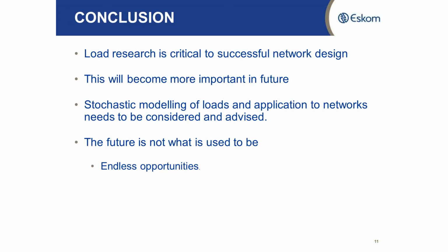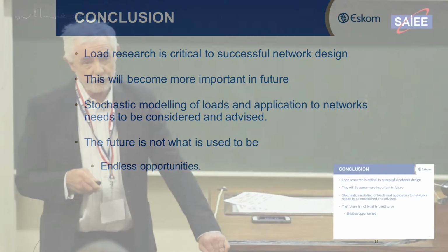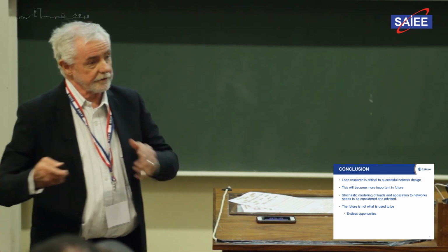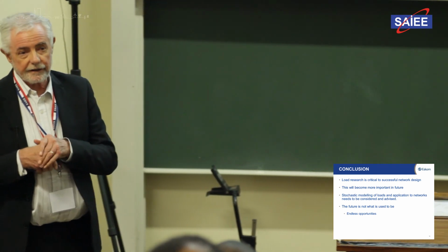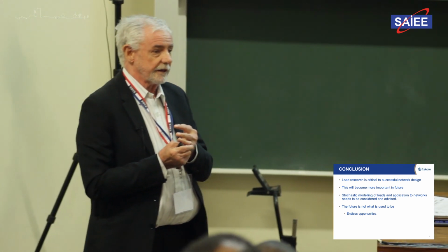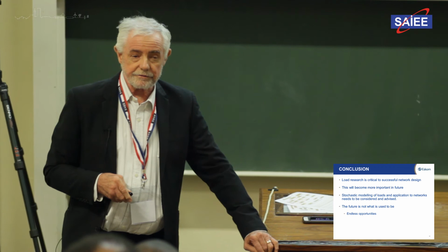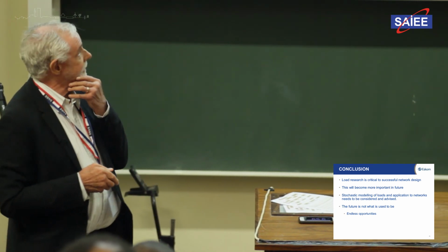But if you want to get into some really exciting stuff, I think load forecasting and load modeling. Marcus mentioned that at the moment we've got about 10 to the 12 data points. So you need to start looking at big data management on load research. And this is going to get more and more. They're starting to even use PMUs in MV networks overseas now because of the instability of the operation. And then you're starting to get big data coming in. And in 6 months, you can get 10 to the 12 data points. And now you actually start managing all this stuff. So these kinds of things are getting quite exciting.